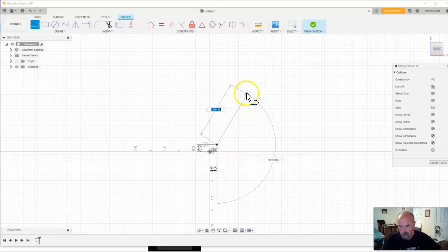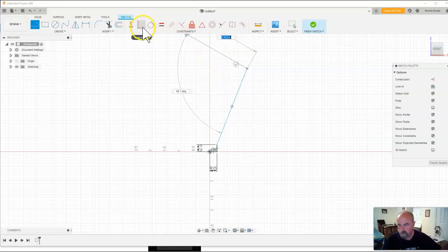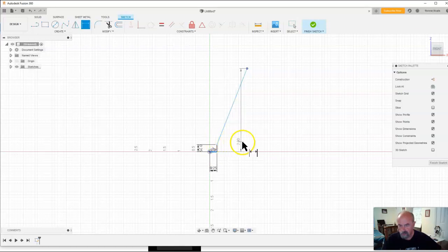And then I'm just going to come up here somewhere and click. And I'm going to dimension this, come over here to this bottom line, click on that, drag this over, and I'm going to make that 1.5.